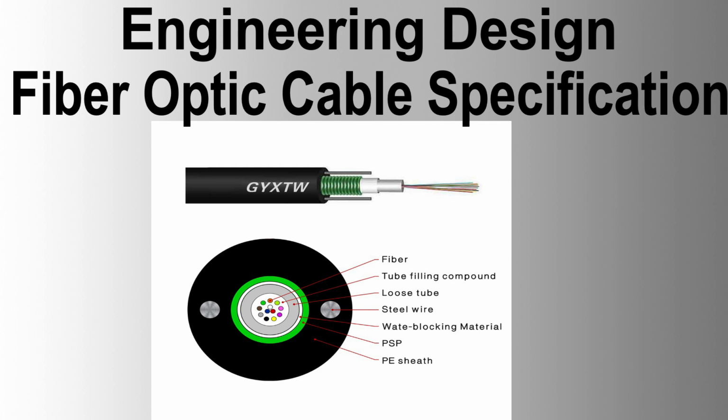Construction. The cable must be of stranded, loose buffer construction where fibers are contained in a series of tubes. Thixotropic gel. Inside the tubes, filled with a thixotropic gel to prevent moisture ingress. This compound must be non-toxic, dermatologically safe, free from foreign matter, chemically and mechanically compatible with all cable components, non-nutritive to fungus, non-hygroscopic, and electrically non-conductive.